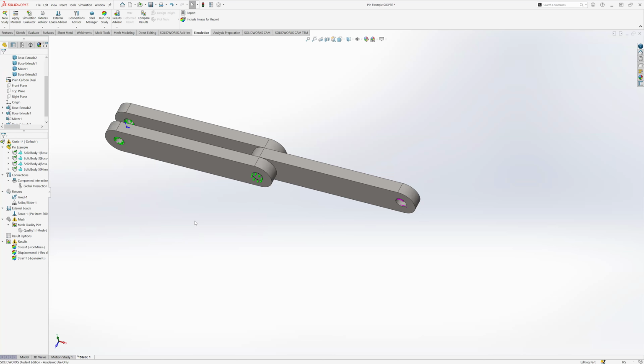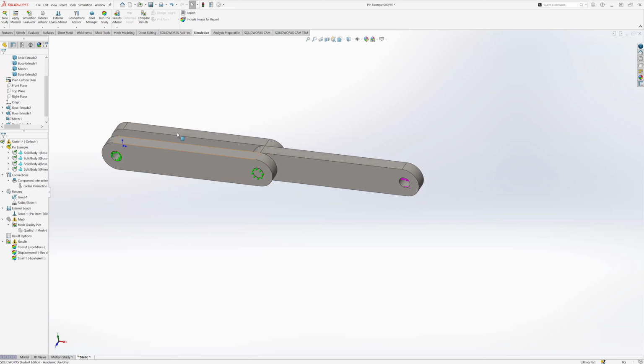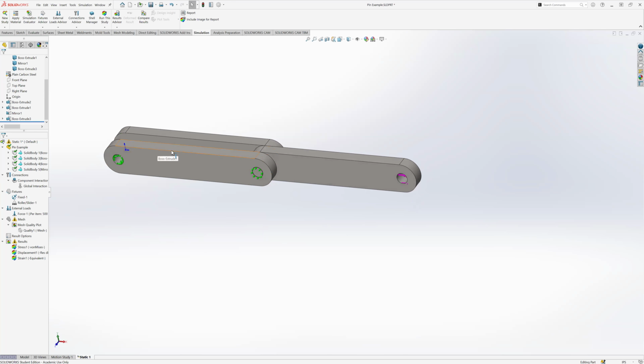In this scenario, I could also go back and put that roller slider on these top faces, but I'm going to try to run it without those first. If I put a roller slider here, that's not going to be very realistic behavior, because with a linkage like this, like I was saying with the Poisson's ratio, it's not realistic for it to not shrink in this direction. You're going to expect to see it shrink in both directions.